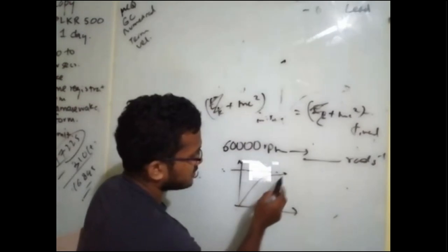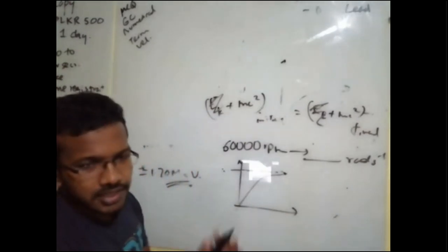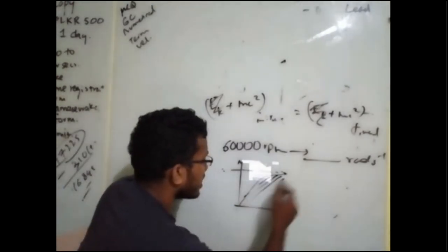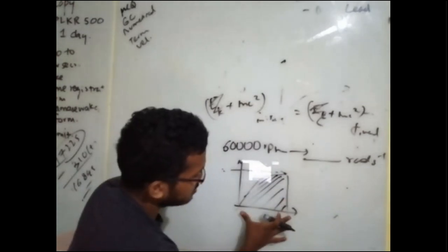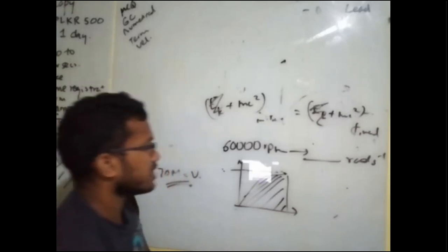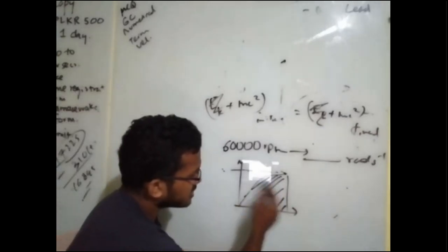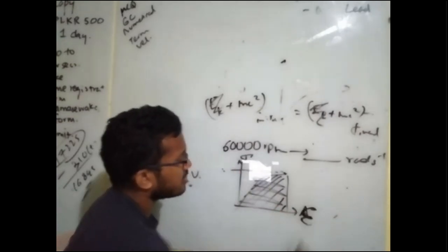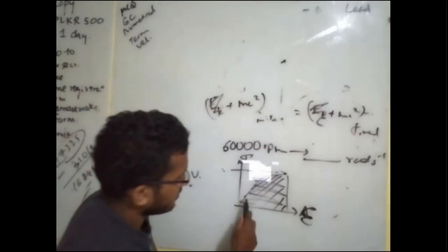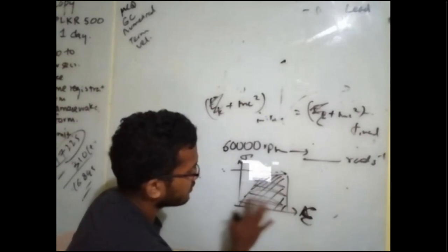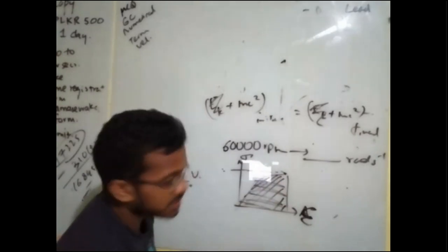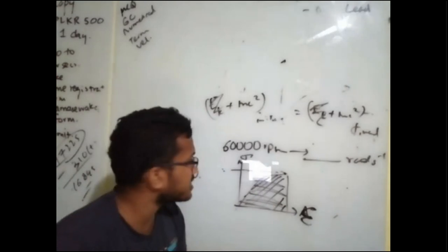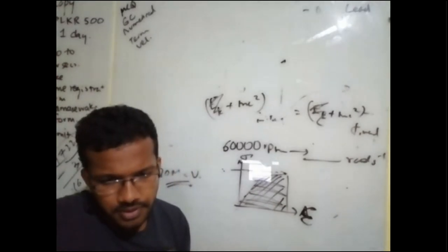Called ultimate tensile stress. If something has a high ultimate tensile stress, it has a high strength. Then if the area under the graph is high, that's a combination of a large extension before fracture and high Young modulus. Those two combinations give a large surface area, which, on a stress versus strain graph, is an energy density. It can absorb a lot of energy per unit volume before fracture. That's called toughness. But since it's state, old syllabus guys can just say high strength and high toughness.